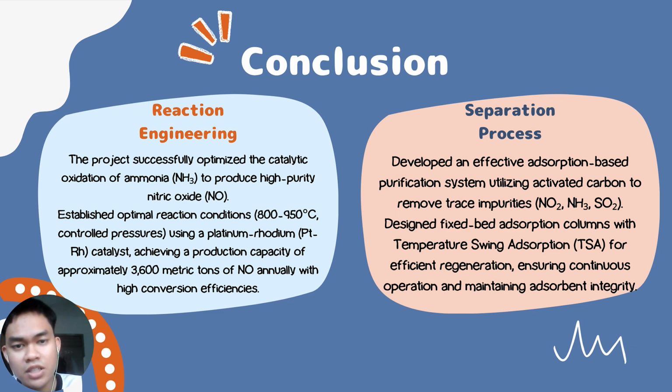And for the separation process part, we have also developed an effective adsorption-based purification system which utilizes activated carbon to remove traces of impurities like NO2 and excess NH3 and SO2. We have also designed the fixed bed adsorption column with a temperature swing adsorption for efficient regeneration. And we have ensured a continuous operation and maintained the adsorbent integrity.